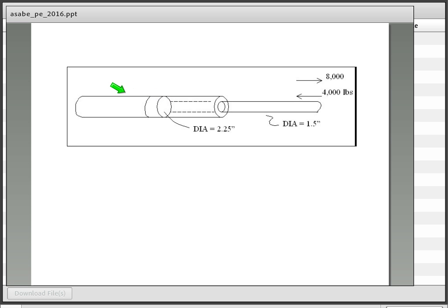So you're only dealing with that annulus there for cross-sectional area. So forces involved would be cross-sectional area times pressure. And over here, the retraction force capability would be that annulus cross-sectional area times whatever pressure there is in the rod end of the cylinder.